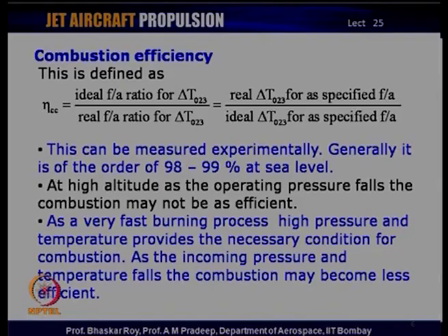So, the ratio of these two, the ideal and the real, is often defined as the combustion efficiency. Now, in a test rig, it is easier to measure the temperature rise across the combustion chamber. On the other hand, for the operator, it is easier to measure the fuel flow and the fuel air ratio, as a result of which both the definitions are often used alternately to obtain the combustion efficiency.